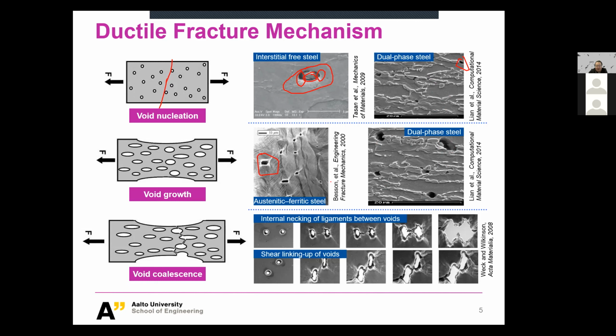This is easy to imagine, but what is interesting is, when you really develop large enough voids, what will happen? So this is so-called void coalescence. I told you, some voids are going to meet each other and they develop a big one. So how are they going to meet each other? And here's the point: this process is taking place really fast. You don't see it via a microscope, because it's usually happening inside of the material. When we see the fracture, so the material becomes two parts, it is already too late.